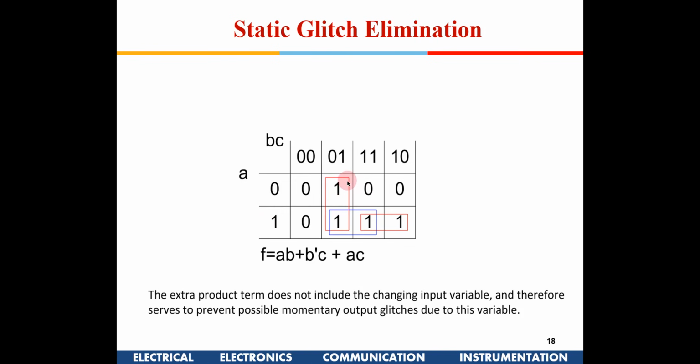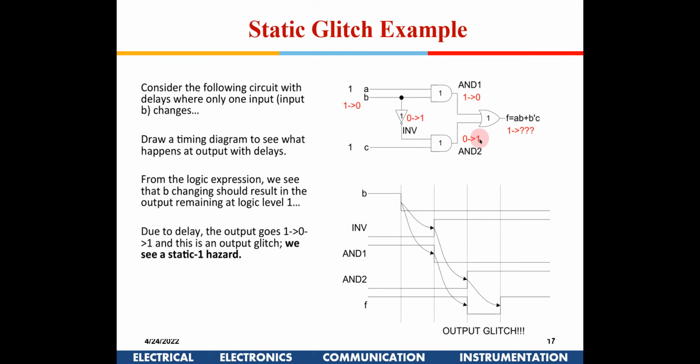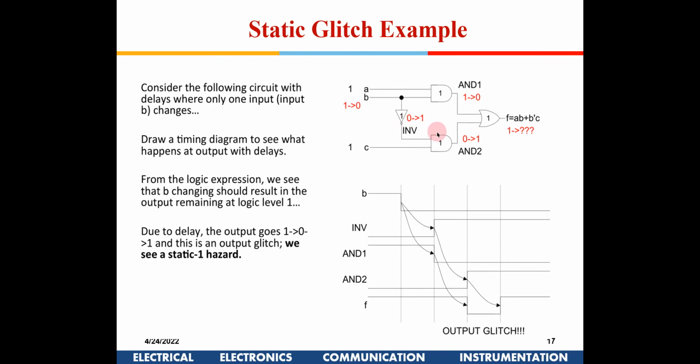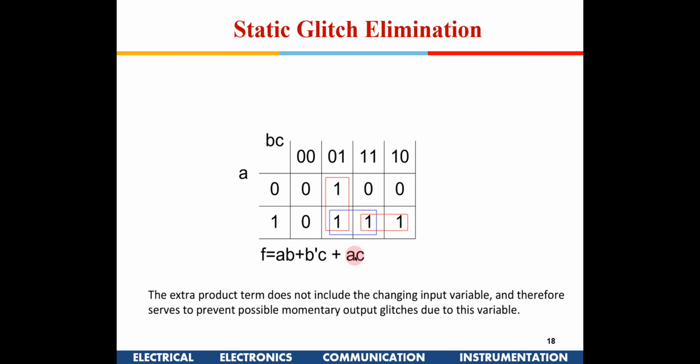So I make a K-map, the red ones, the 1 1 and 1 1. If I do this, this is the circuit which gets implemented. If I club these two and these two, there are adjacent cells which I have left, which I did not cater to here, right?